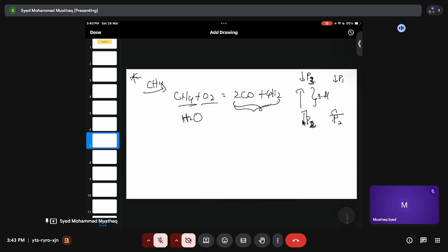Now see, whenever we are trying to use a blast furnace, there are disadvantages. The main disadvantage is you cannot control the composition of pig iron from batch to batch or from tap to tap, right? Tapping is nothing but taking out the liquid metal from the hearth. So you cannot have good control over the composition. And again, high operating and controlling cost. Why?